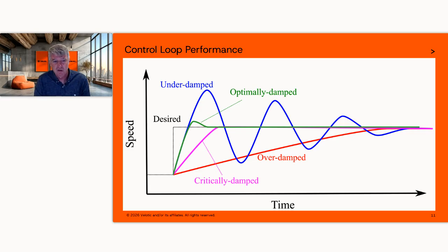So there's a condition they call overdamped, where imagine you have a really timid driver and they barely touch the accelerator. You do eventually get to 65 miles an hour from 55, but it takes a long time. The other thing is you have a brand new teenage driver, and what they do is slam on the gas, and then they're like, oh wow, I'm going 70, and they hit the brake, and now they're down to 60, and then they hit the accelerator again, right? Again, this is a lot of oscillation. This is called underdamped. You don't want that either, right? It's a really jerky process.